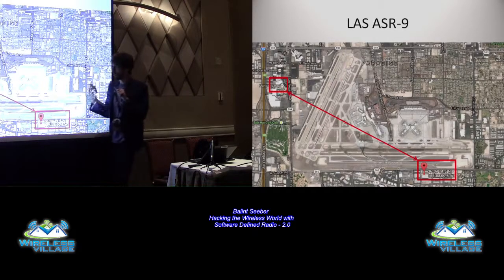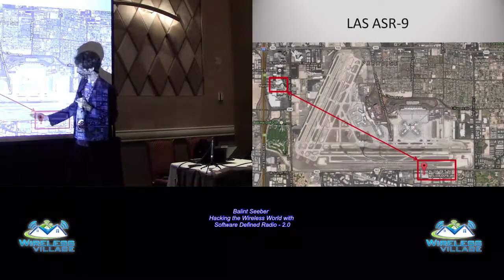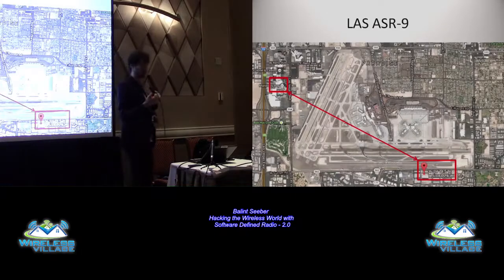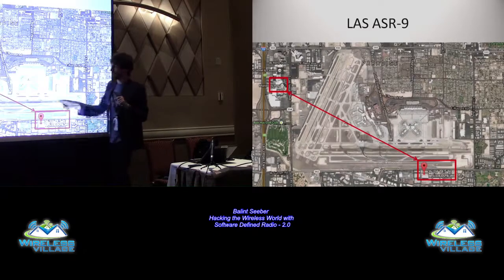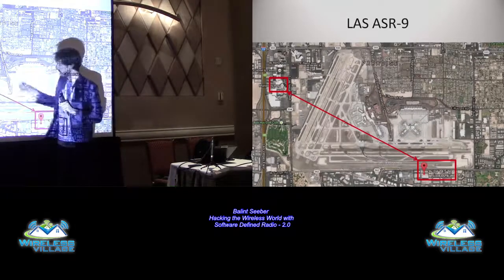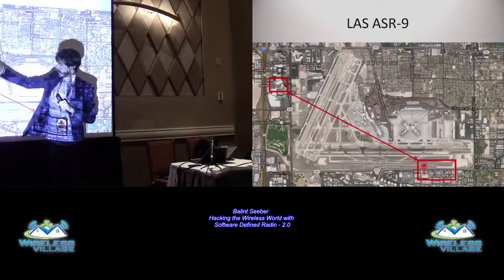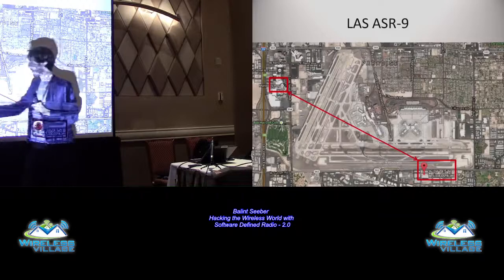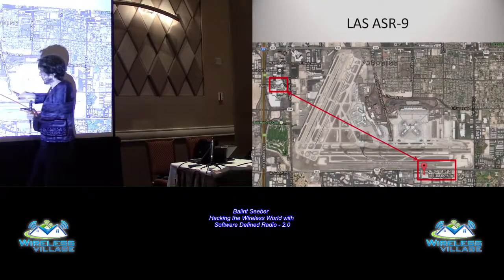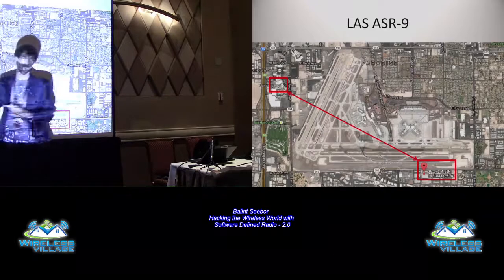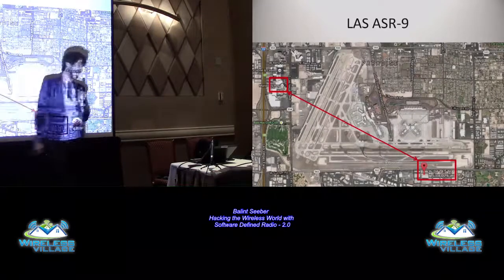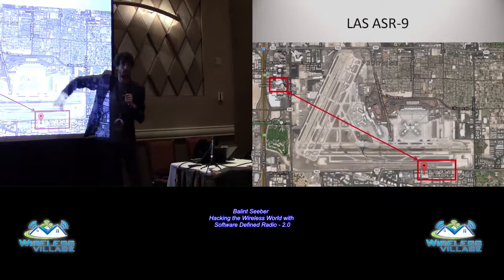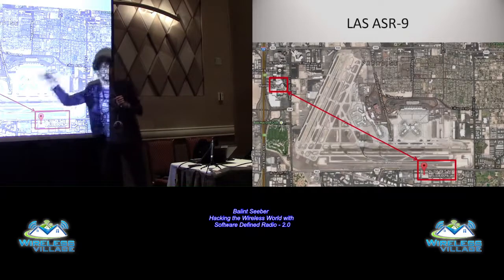And if you think about why, when the radar spins and turns and points in my direction there, it's going to not only saturate the receiver because it's so powerful, but if there's some other object around here, you're receiving samples and you need to consider the flight time of your wave, of your photons. So you consider the main pulse coming out, it's going to go off something here, come back together, and it's just going to be hidden underneath all of the main energy. So when you want to track objects in this kind of separated bistatic setup, they have to be further out.